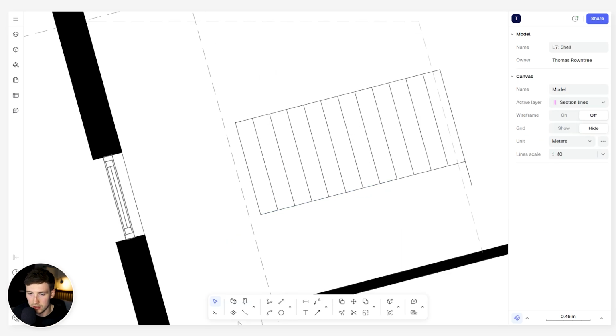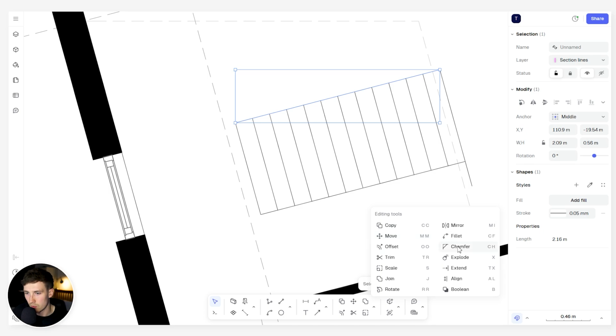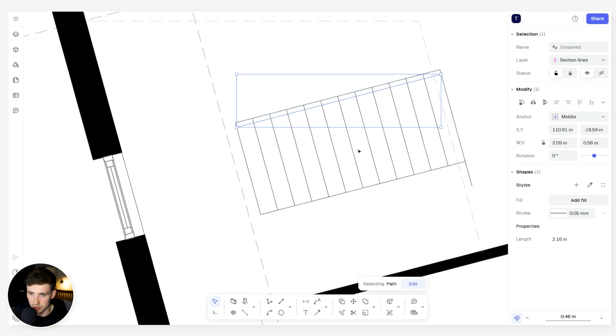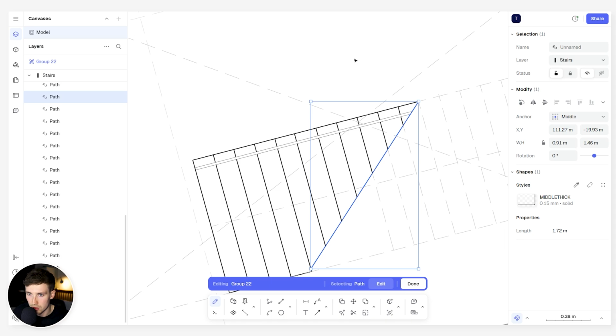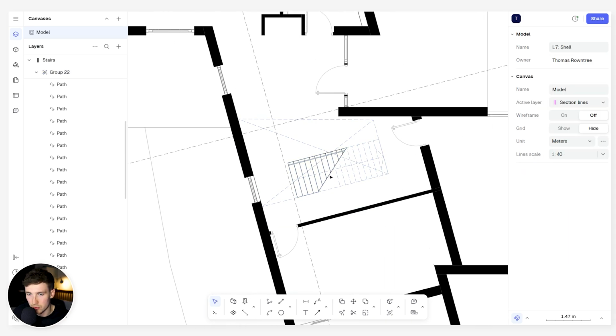And then we'll obviously start adding some more detailing with the balustrading, so we can also offset that with maybe, let's say, 100mm balustrading, so 0.1. Maybe we don't want 100mm, that's quite thick. Maybe we'll go 0.05, so 50mm balustrade. And if we also indicate the cut at which the stair is being sliced through on the upper floor, we can get something like this.